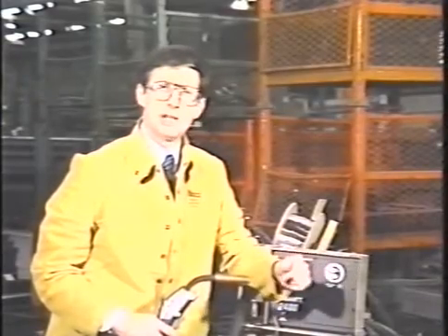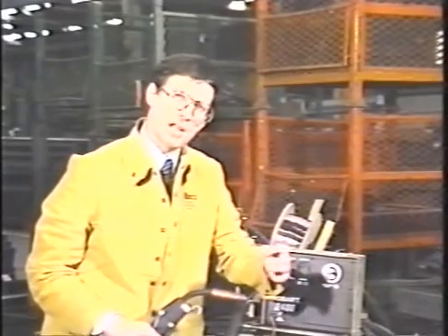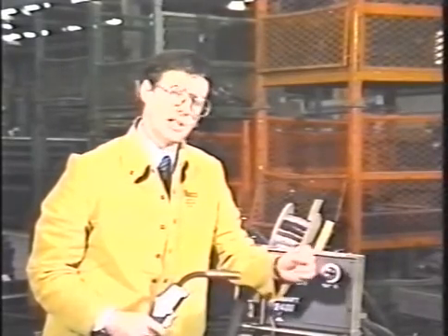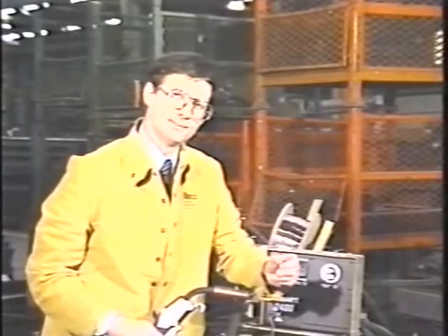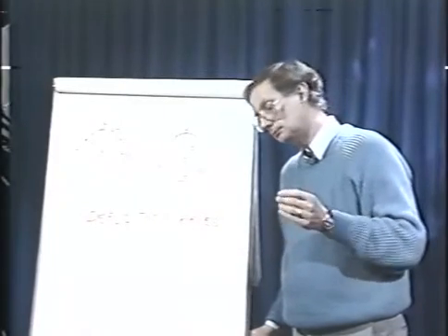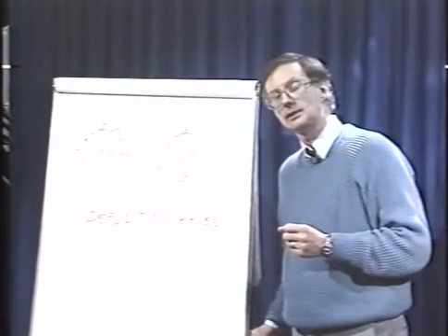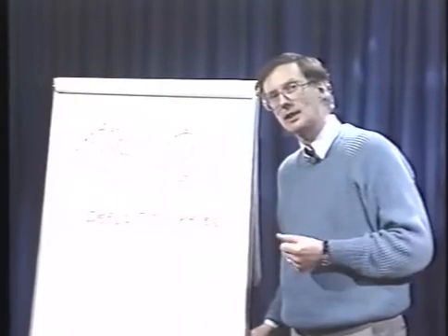We can also achieve the same high depositions by just increasing the current. We get very good arc stability, a slightly wider voltage coverage off the larger wire. All the economical sense is there. It costs less, it's better to use. So consider 045 wire for your next spray application. In the fabricating industry, if we can achieve 12 to 15 pounds an hour in terms of deposition rates, then we've truly got a handle on our cost.